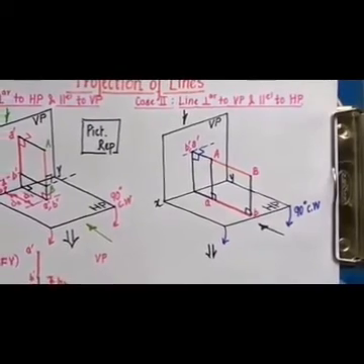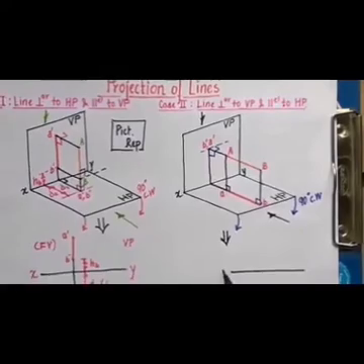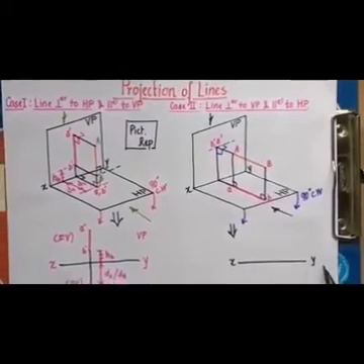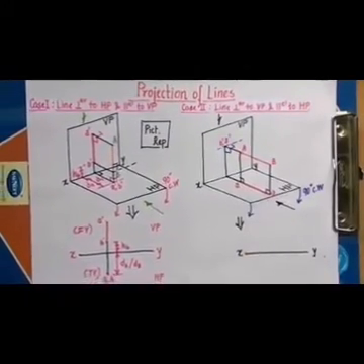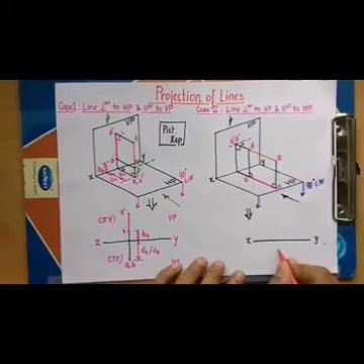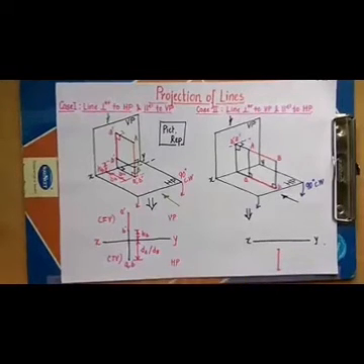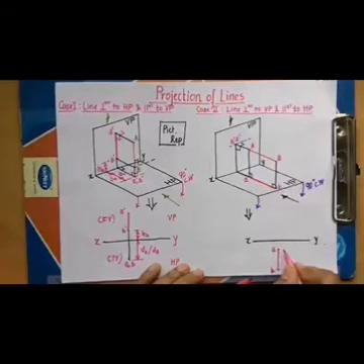Please let me show this to you. This is the so-called XY line. This is going to be the top view. We begin with the top view because the true length of this line can be seen from the top. For drawing this top view I have this point A and I have this B. I know the true length of the line, but how far this endpoint A is from the vertical plane is something that we need to know. So this is going to be DA.